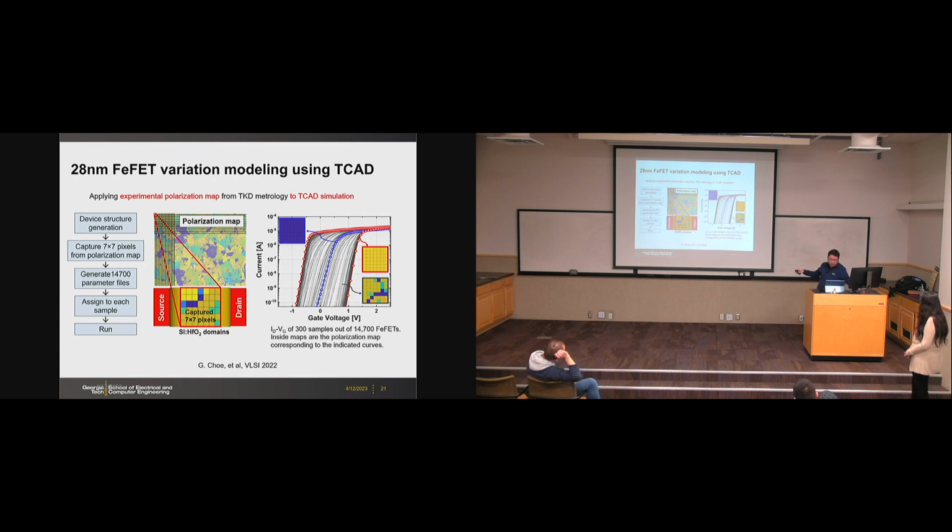So here, the experiments we have are the metrology data. This is the only experiment we have. Of course, we use TCAD to predict the ID-VG characteristics. But we haven't validated, let's say, if you make the real transistor with this thin film, what would be the characteristic? So there's no calibration on that. Our input is the raw data from the thin film. You do the imaging, and then you get this kind of map.